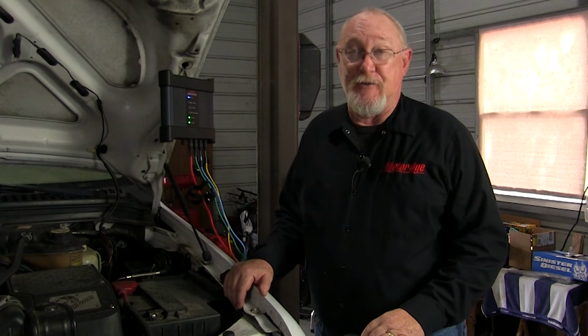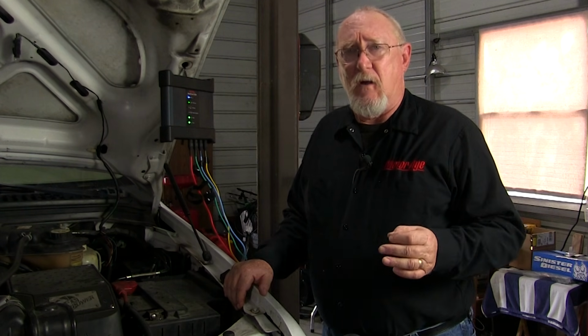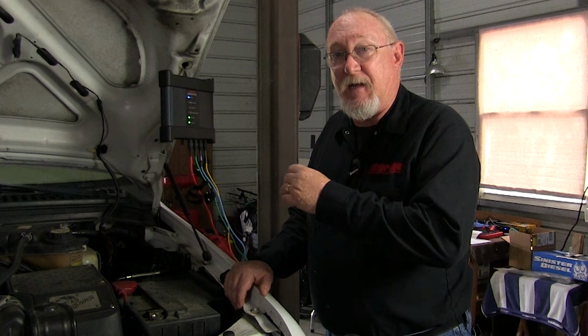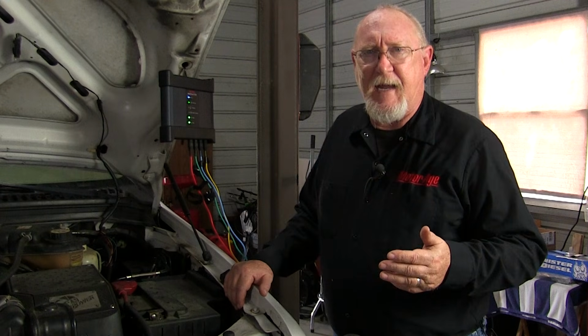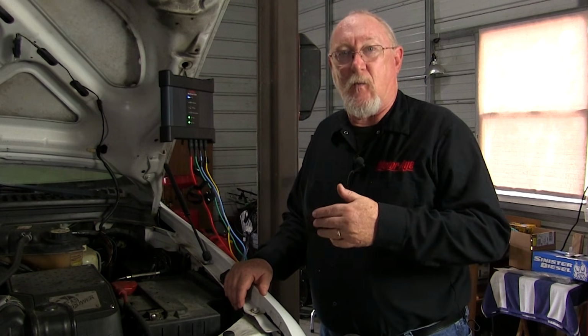in on that module. I'd like to know, are there CAN signals present at the module? If not, there could be a break in the CAN network between the module and the point where it splices into the bus. I also need to be very sure that I check and verify that the module has good power and grounds. Any electrical component, no matter what it is, cannot function properly if it's not getting a clean source of power and a good path back to ground.